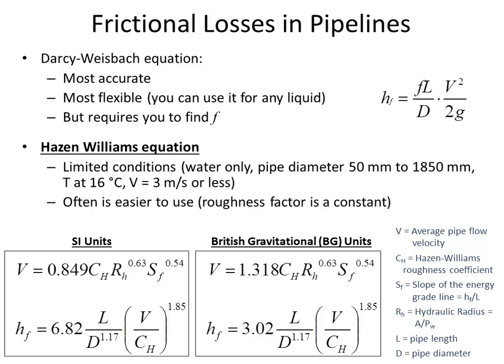The other way to look at the Hazen-Williams equation is its ability to tell you what is the energy loss for a known velocity, for a known pipeline length, known diameter, known friction. And so there are really two different types of questions that it gets asked in. If you have a defined energy situation and want to know how will the water respond, or if you know what the water is doing and you're curious to know how much head loss there is. Two sides of the same coin.